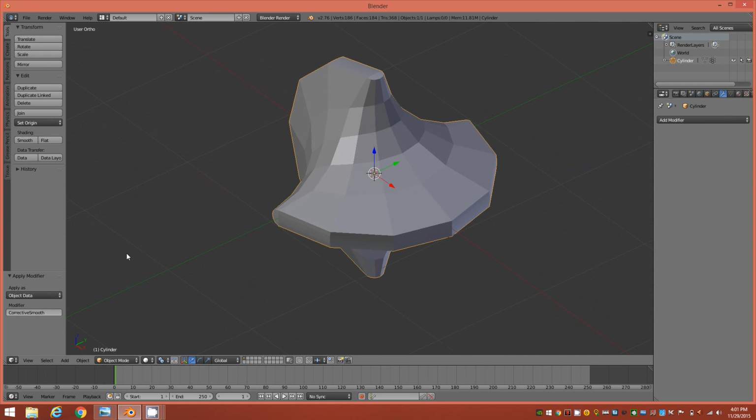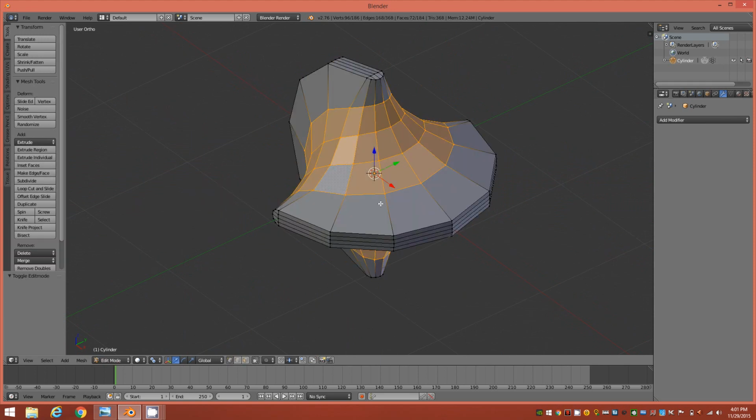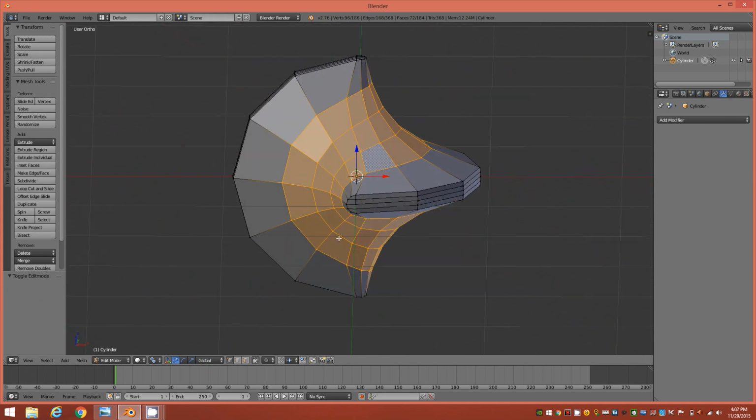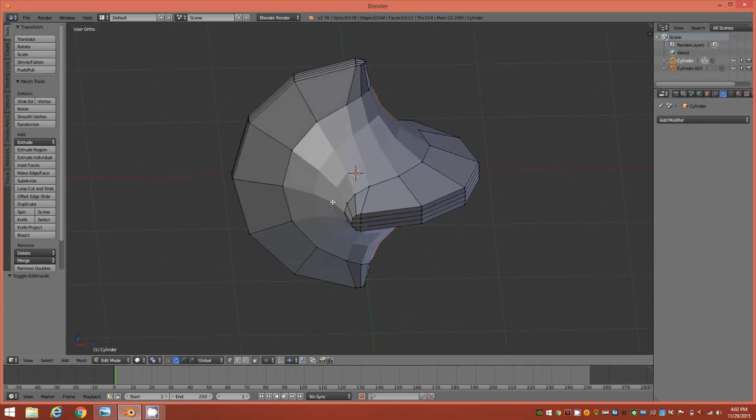We're going to go now to edit mode. And our vertices here are still selected, which is what we want. Because right now we'll tap the P key to separate, and we'll separate by selection. That separates this middle web from the curved edge parts. So this is what we have now. This has been separated to an entirely different object, which will allow us to work on this part without affecting that. But for now we're going to tab out to object mode again.